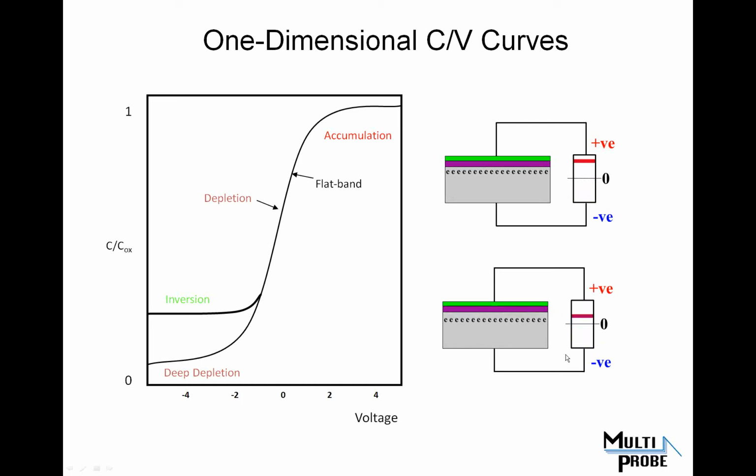Whereas when you're moving the signal fast enough, the depletion changes all the way through, and you get into what's called a deep depletion curve. So in the AC capacitance that people typically use, it would be more the curve on the bottom, the deep depletion curve. The reason being that your AC frequency is usually measured in kilohertz, up to maybe 100 kilohertz.